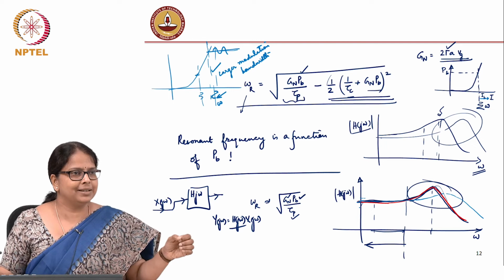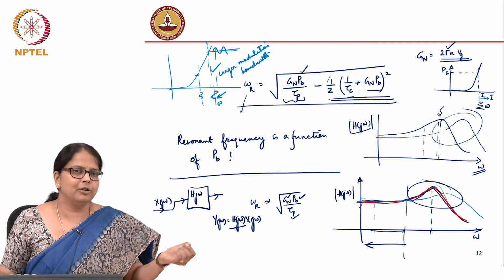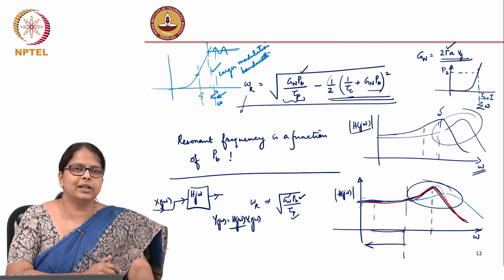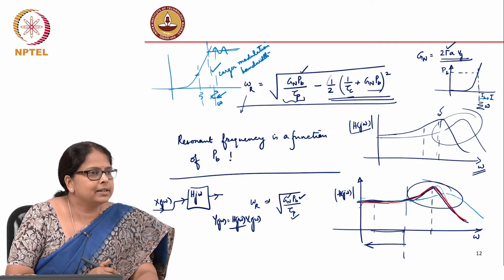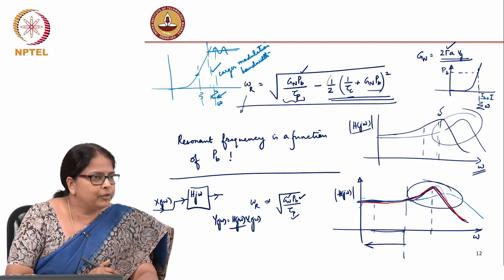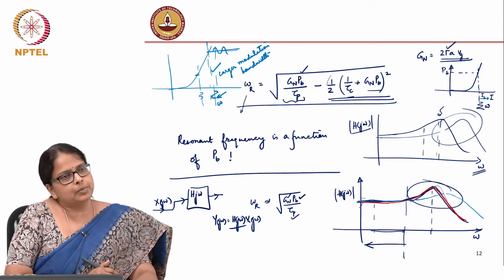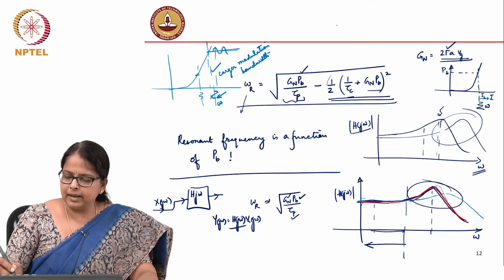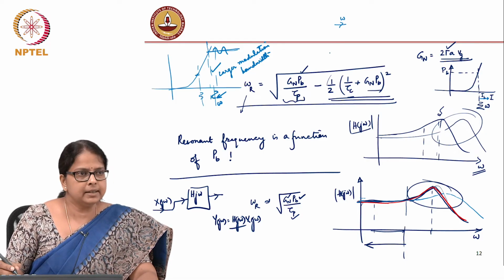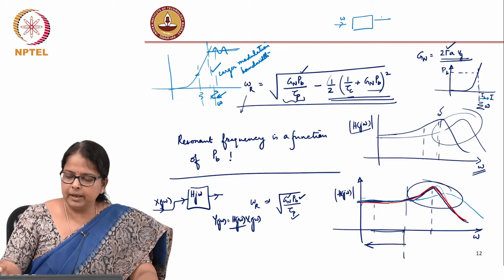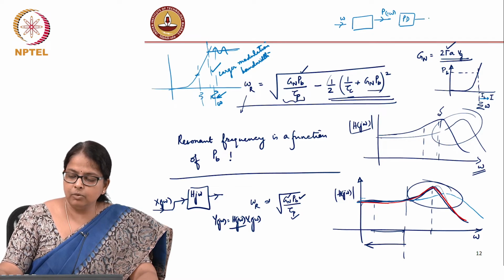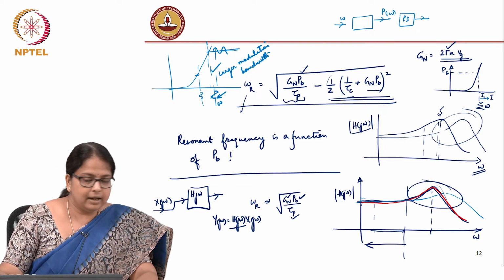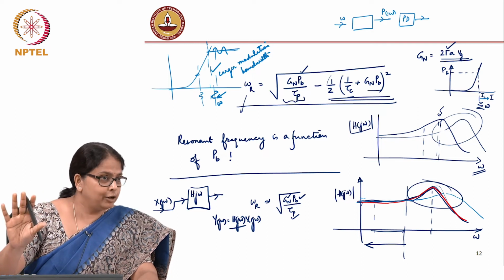And how does one characterize it? Just like how you would do a transistor frequency response characterization, you change the input frequencies, you look at the response in the optical domain. So, you will excite the system with different frequencies. The system will give you optical power as a function of frequency, that you will have to put on a photodetector, because you want to convert it into an electrical signal, and assume that the photodetector is not limiting any of the bandwidth of the system.